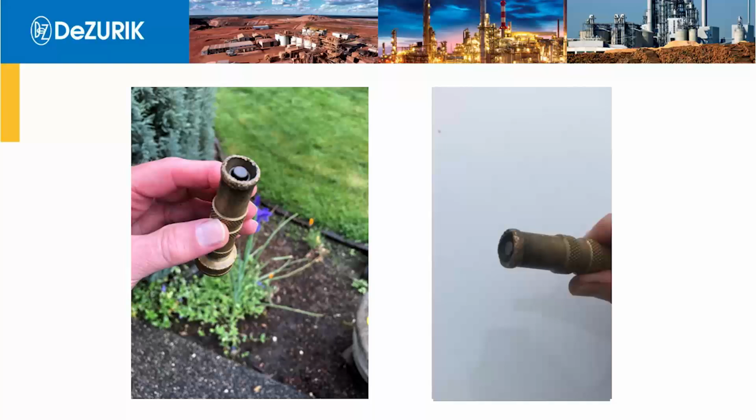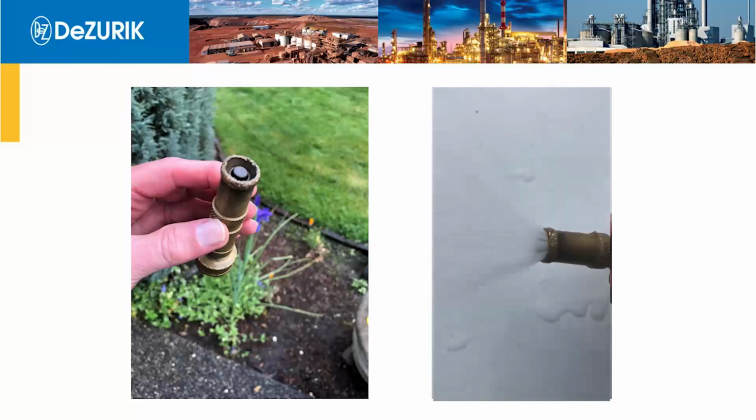And most of you have probably operated a fixed cone valve. So your standard hose sweeper is a type of fixed cone valve. Basically, this is the same discharge that you would see out of a fixed cone valve. It's a 45-degree kind of radial discharge. Pulling the sleeve back is the equivalent of pulling the gate back on a fixed cone valve. And then if you slide the gate forward, it closes it. So that's the same principle that a fixed cone valve operates on.